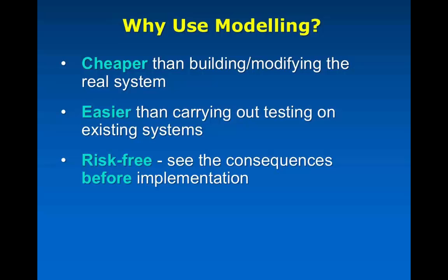In many places, if you were to change your wastage rate, for example, you would probably have to wait at least 2 weeks to find out where that new mixed liquor was going to equilibrate. Whereas in models, you get the answers pretty much instantaneously. So modeling is a useful tool because it allows you to do a lot of analysis in a very easy, straightforward way and get the results back pretty much instantaneously.